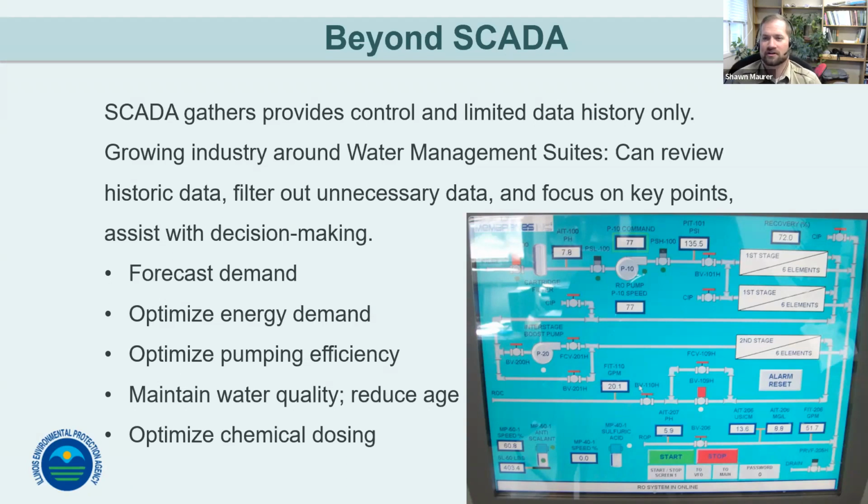Maintaining water quality. We're talking about distribution networks. One of the things to be concerned with there is the age of the water. The longer that water's been sitting in the distribution network, now you've got greater risk of disinfection byproducts from chlorine in there, leaching of chemicals from pipe walls for those of us working on lead and copper lines and haven't replaced those yet. Water turnover, and making sure that that's not too old is going to help ensure that that water is still clean and usable. And so a lot of water networks do periodic flushing of dead end legs and of systems and things to help control that water age.